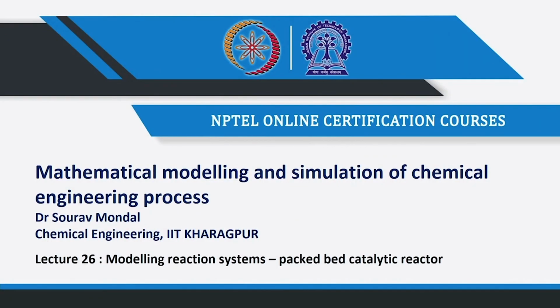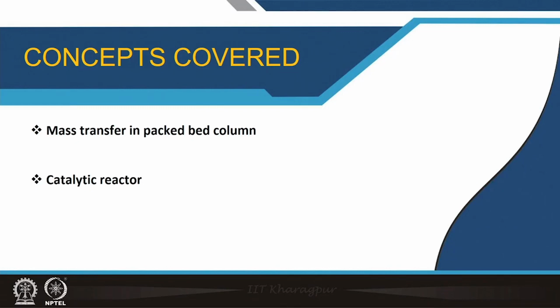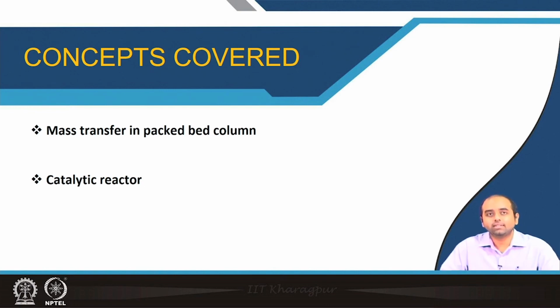Hello everyone, in this week we are going to talk about reactor problems, particularly focusing on catalytic reactions, heterogeneous catalysis, packed bed reactor, enzymatic reaction systems. Okay. So, today the first lecture we are going to focus on general packed bed catalytic reactor. I mean how we can model them and what are the background of this process. So, essentially we will be talking about heterogeneous catalysis problem in this case, and how the mass transfer in a packed bed column is intricately coupled to this catalytic reactor process.